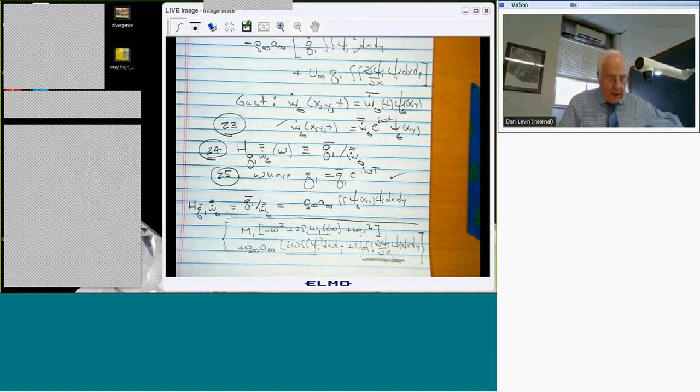Okay, so what do we conclude from this? Remember, this is a one mode model. So what I've said is, in one mode, the only thing that can happen is you can have negative aerodynamic damping, which is not true of piston theory, but it's true of some other aerodynamic theories. Or you could have a loss of stiffness, which means you could predict divergence with this model.